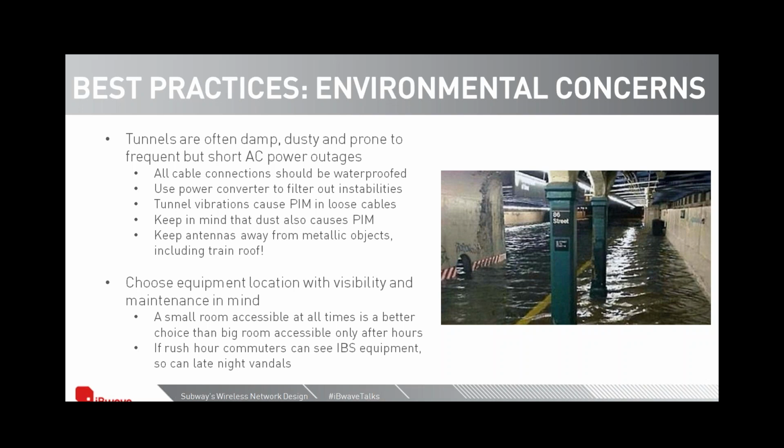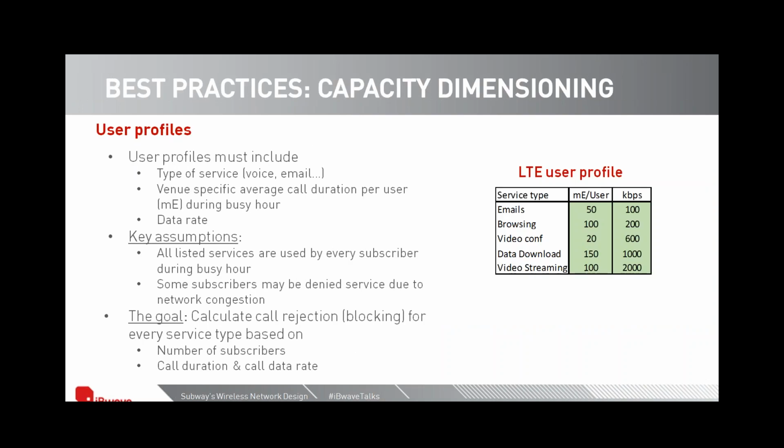And now we're going to spend the next 15 minutes or so talking about capacity dimensioning. The first step is user profiles. We need to define a user profile for each technology, and that is done by defining the type of service, the venue-specific average call duration in milliErlangs per user during busy hour, and data rates.